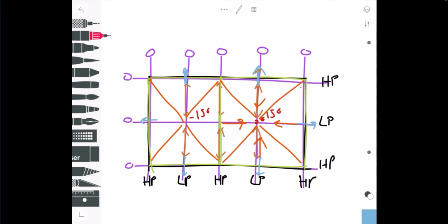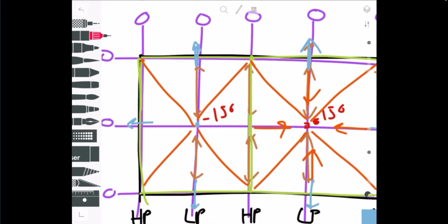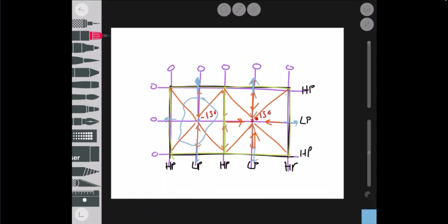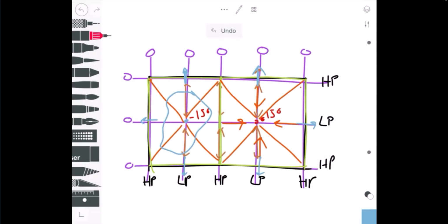And really what that is, if this roof drain right here got plugged up and water started to pool on the roof, it's only going to pool so much, and the engineer can design to that. And then at some point, as the pooling happens, it's going to go through those emergency overflow scuppers, they're called. So that's one option. That's the most common option because it's quite cheap to do. Again, not always possible to do the overflow scuppers.